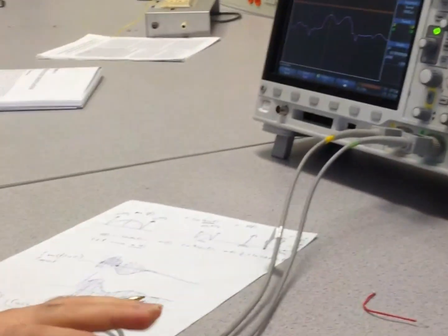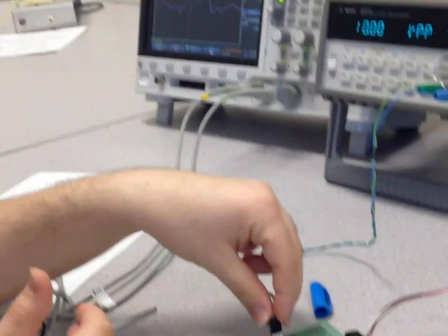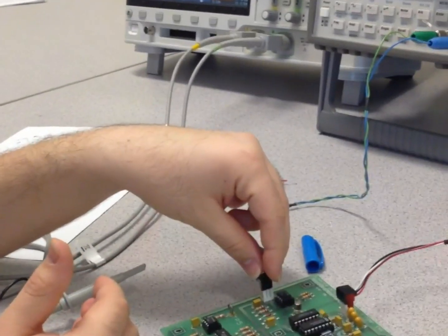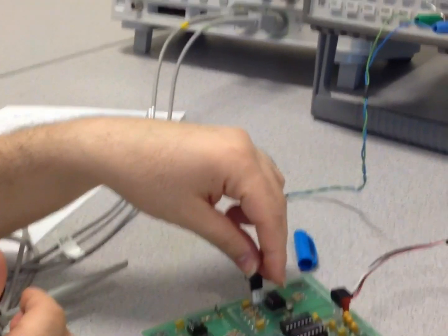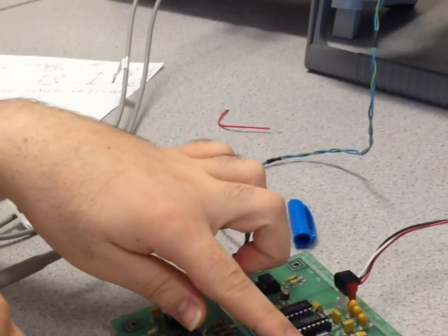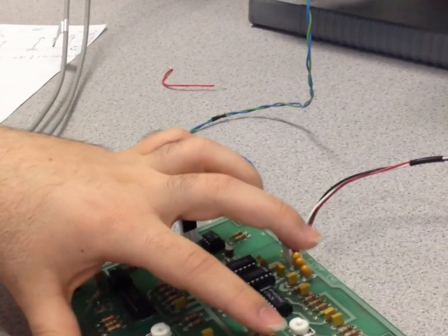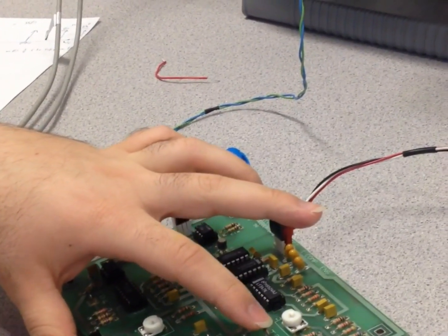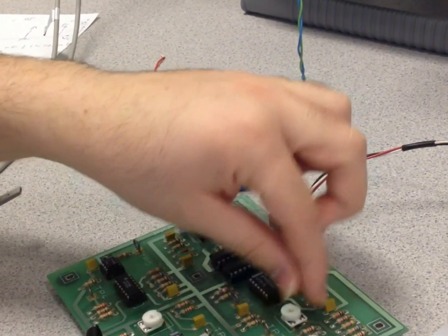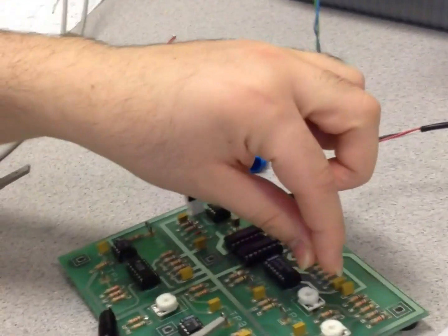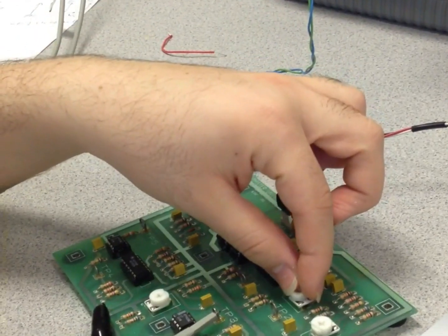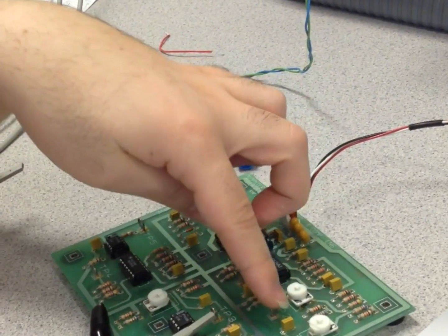So to summarize what we are going to do here, we have a double sideband suppressed carrier signal. We have an input 64 kilohertz signal. The 64 kilohertz signal, by comparator, I change it to a square wave of 64 kilohertz, divide by 16, and I get my square wave 4 kilohertz signal. This signal I pass through a low pass filter to get a 4 kilohertz sinusoidal. The amplitude of this sinusoidal is controlled by potentiometer 1, and could be seen in TP2.